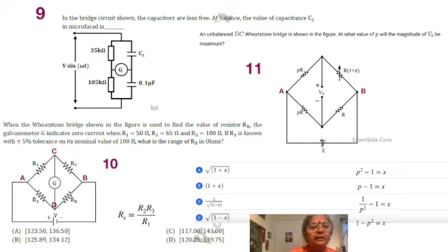Okay, so we have 35 by 105 kilo ohms. So 35 by 105 or 105 by 35, which is better because then you can write it as equal to C1 by 0.1 microfarad. Okay, so 105 by 35, immediately a feel for numbers tells you it's equal to 3, and 0.1 by C1 gives you C1 as equal to 0.1 into 3 or 0.3 microfarad.